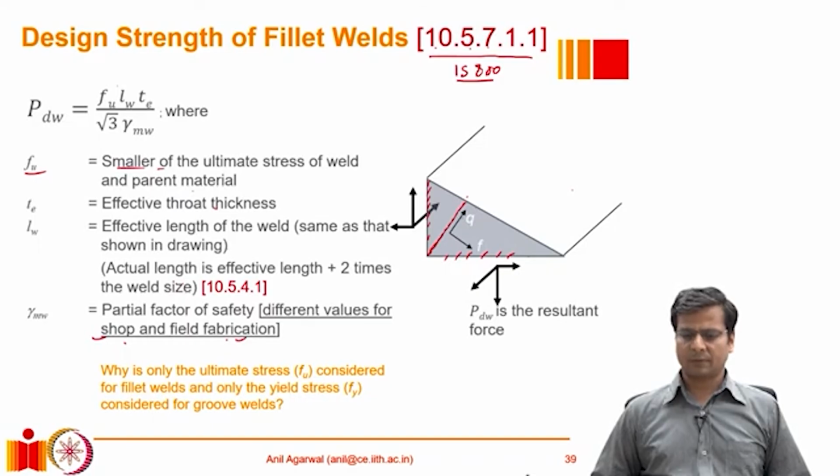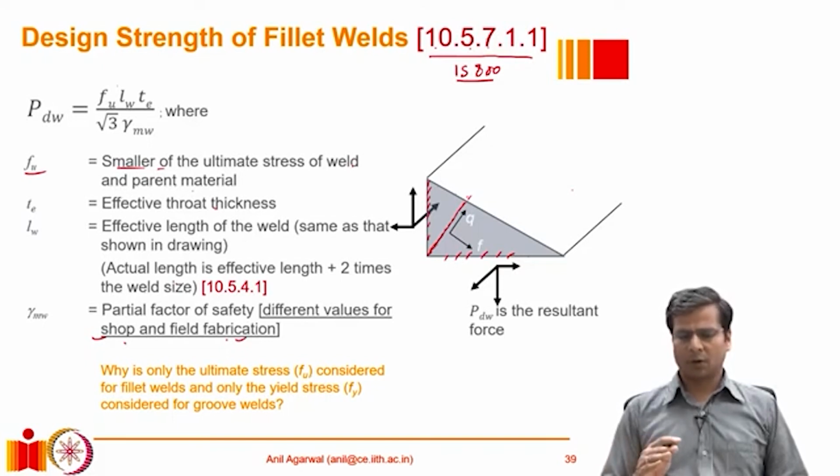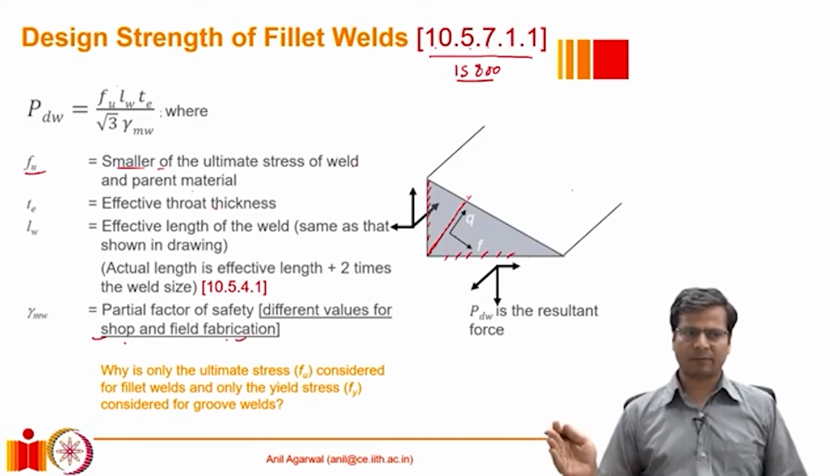And that makes quite a bit of conservative sense, because a ductile material, as we know, has the lowest strength in pure shear. Whenever we have a ductile material, if we calculate using the von Mises criterion its strength under pure tension, a combination of tension and shear, or pure shear, we will always have the lowest strength under pure shear. Therefore, what it is saying is that you take its strength under shear and say that that is its strength, no matter what the loading is.